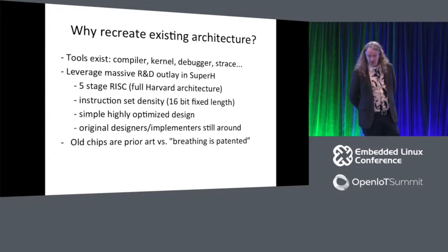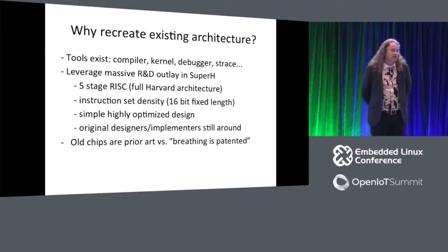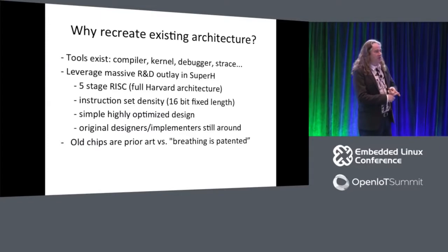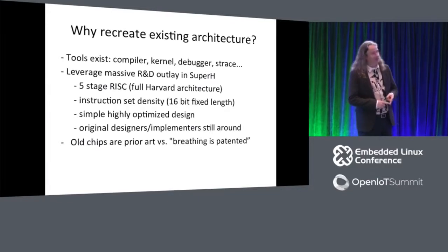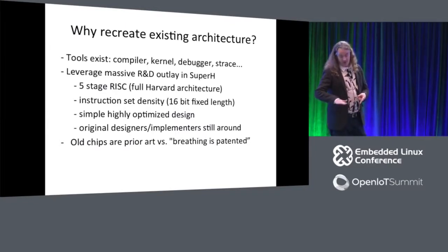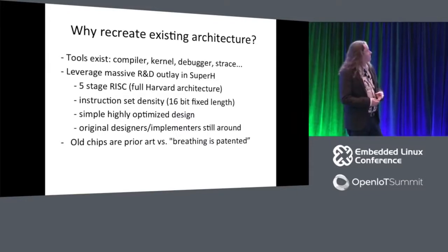When you do very low-level hardware, like what we're talking about, you have a certain set of constraints that you want. We're not talking about a system that has multiple DIMMs for memory in it and 64-bit wide buses and all that stuff. You want a single DRAM chip because now you're talking about the cost of a few cents instead of a few $100s. You want something that's going to be fast enough to execute what you're after, but not necessarily server-class hardware. So that places us where we are. And it has to meet the requirements that we just talked about: 32-bit programming model, GCC support. Hopefully it has existing compilers because you don't necessarily want to do that.